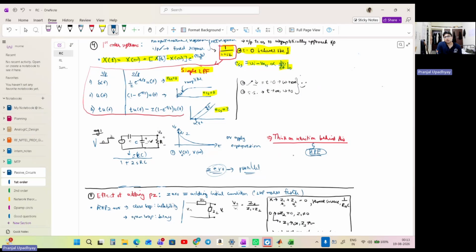That's the basic idea. Let us say that we have some parallel paths. Here we're talking about the voltage at this node, okay? And here also there is some circuitry. Some current is flowing here, some current is flowing here. So you can understand that if this sign is negative, this sign is positive, and these signs are such that they cancel the effect of each other, then because of these parallel paths, a zero is possible over here.